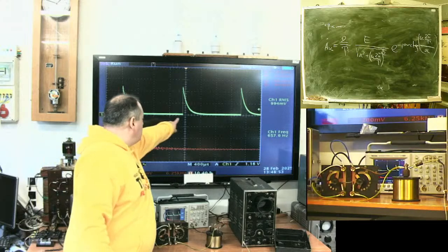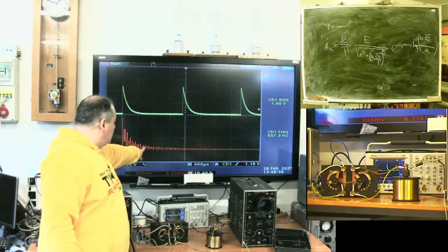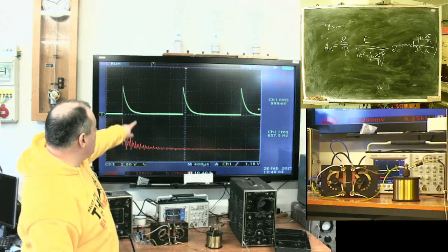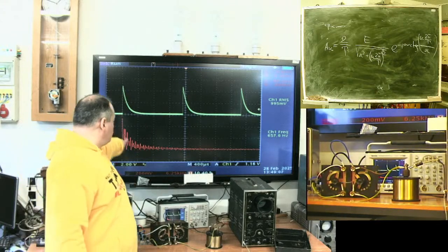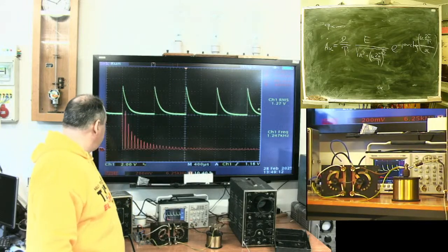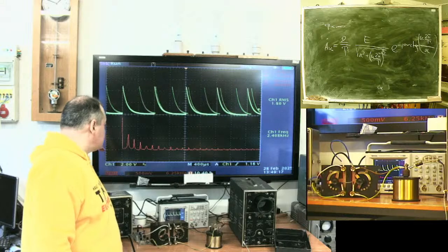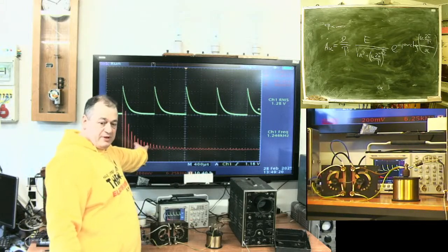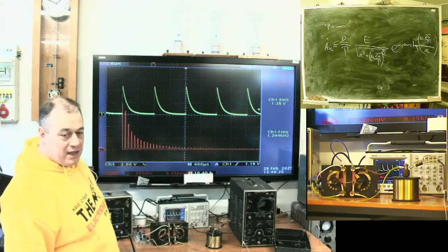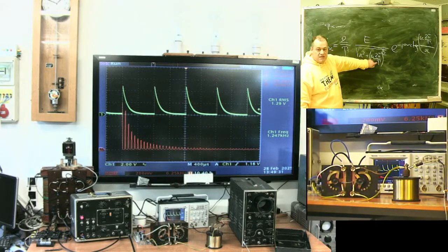The higher the time between pulses, the closer is the spectral line. When only one pulse remains, here should be an uninterrupted area. The closer the pulses, the higher is the gap between spectral lines. It's number one. Understand why? Because here is division by period.